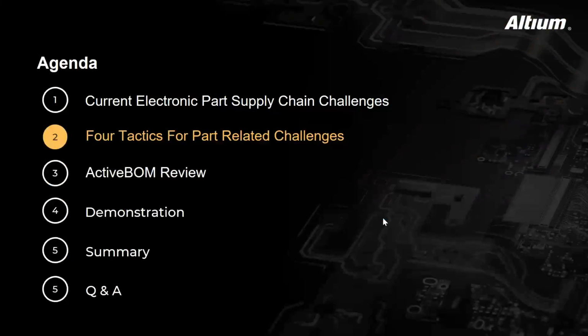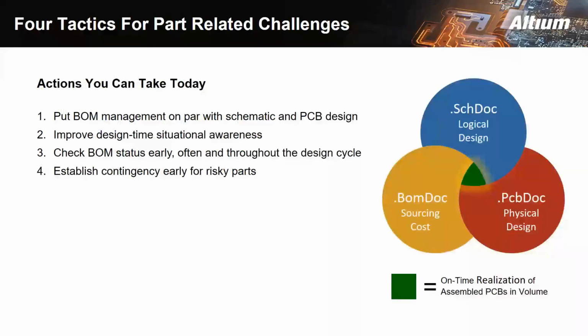And now, let us discuss the 4 tactics for part related challenges. Here are the 4 tactics for part related challenges. Put BOM management on par with schematic and PCB design. Improve design time awareness. Check BOM status early, often, and throughout the design cycle. Establish consistency early for risk parts.